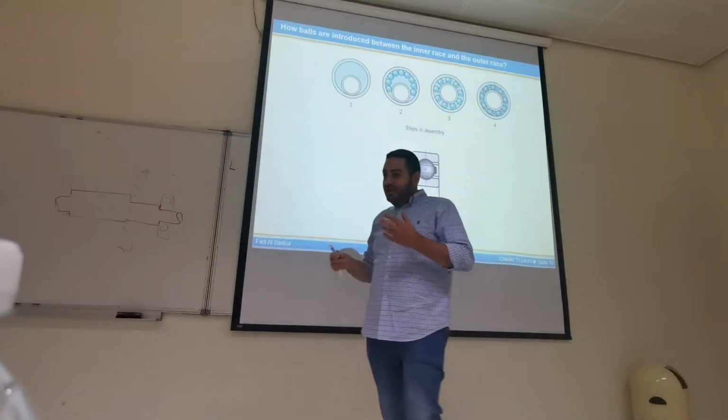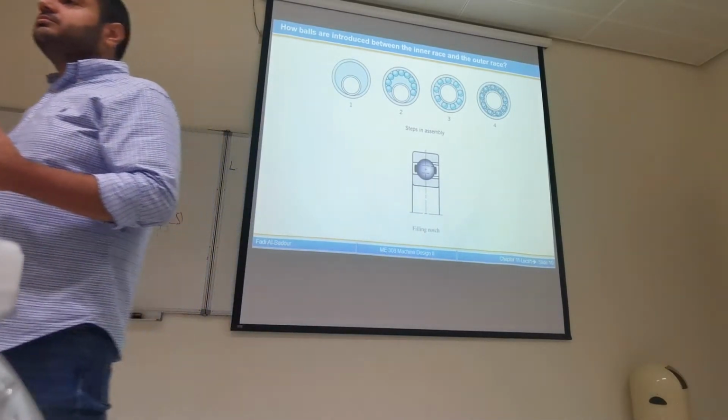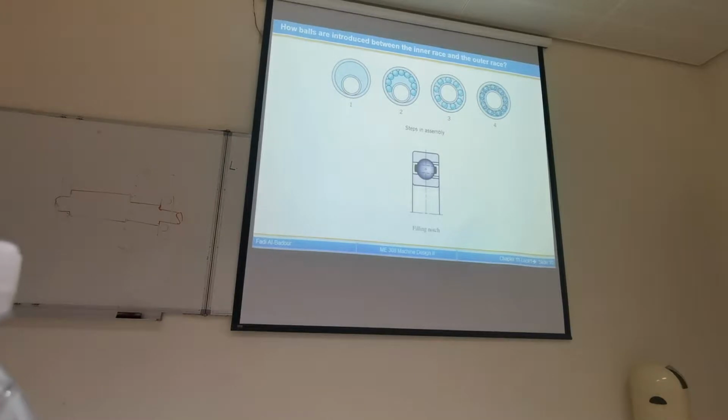But is there any advantage of increasing the number of balls inside the bearing? The bearing can take higher loads. Okay, so there's one advantage of taking higher. What kind of load? Thrust load or radial load? Radial load. But what will happen to the thrust load? Is it going to be the same or is it going to reduce? So his opinion is same.